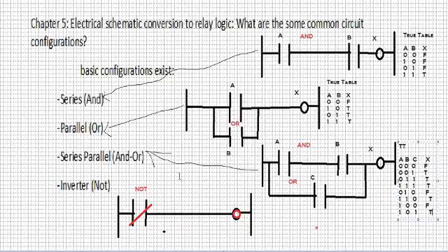And the last truth table, it's a simple one, right? Not so, but anyways, we're going to call this truth table. This is for the NOT or the inverter. And we only have one input, A, and one output, X. We didn't label that, but this is what it is. So this is going to be a little tricky. When the A input is de-energized or 0, you're not going to like this, but X will be true, right? In other words, there's no energy going into this contact for now. But as soon as I act upon it, then X will be false.